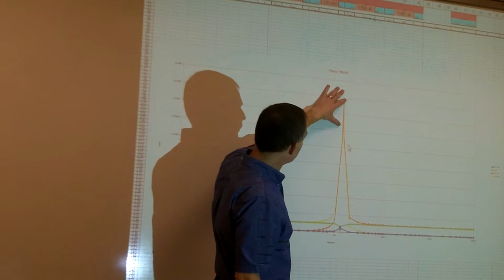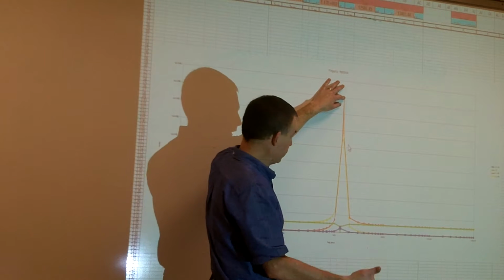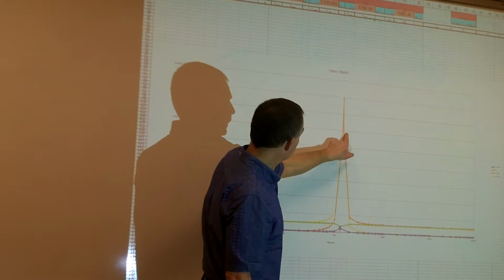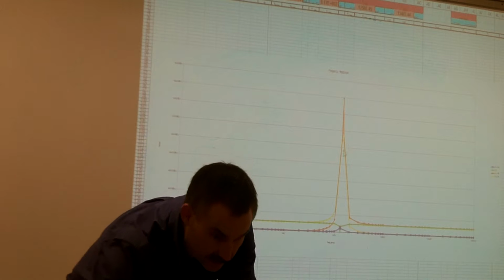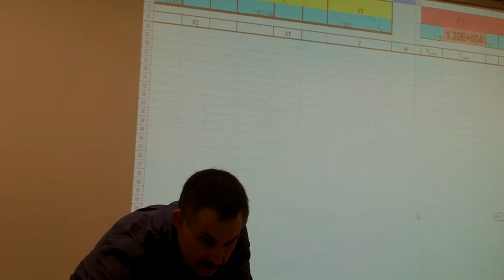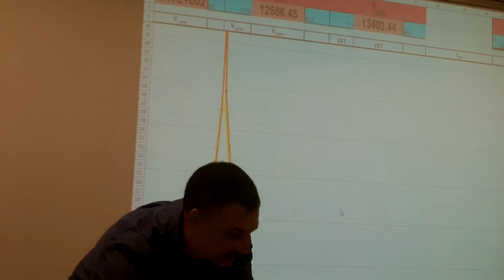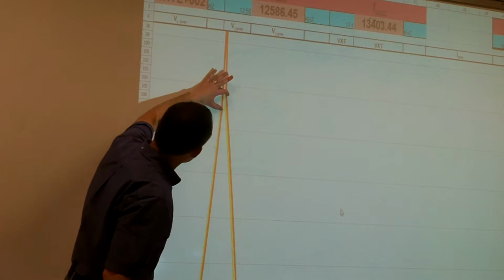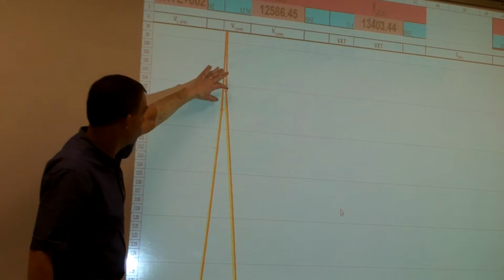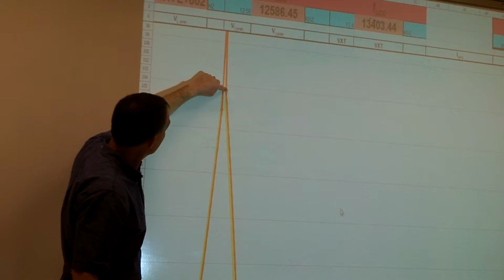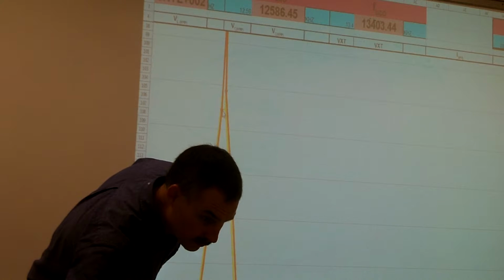So when I'm plotting out certain things, like resonating frequencies, I've got to make sure that I'm plotting out exactly what my resonating frequency is, and then I have 2 data points here, and that's my bandwidth. So my bandwidth is right in that area there. So let me zoom in on that. So here's my bandwidth. You can see I have a pretty narrow bandwidth. I'm only at 816 hertz. That's the difference between this one and this one.